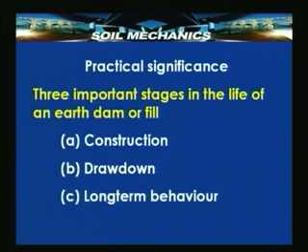As you know, an earth dam is constructed by compaction layer by layer, and during this process of construction water is added to the soil and compaction is carried out, and in this process some pore pressures are bound to be generated, and therefore during the short term of construction period, if the pore pressures which are generated are high, then even due to the self weight and its shear stress component in some specific particular surface of weakness could cause a slide and or a failure of the earth dam.